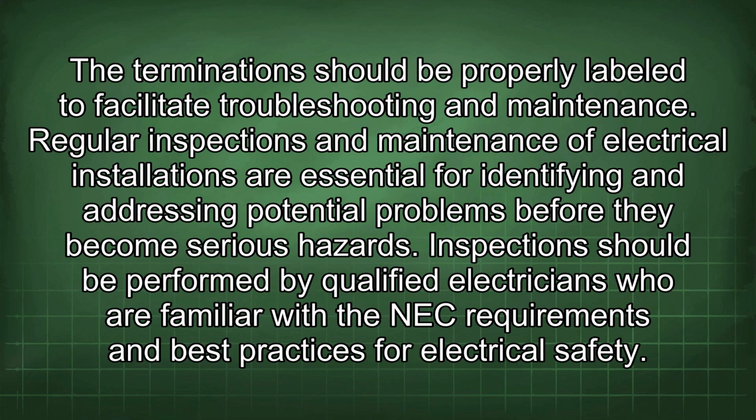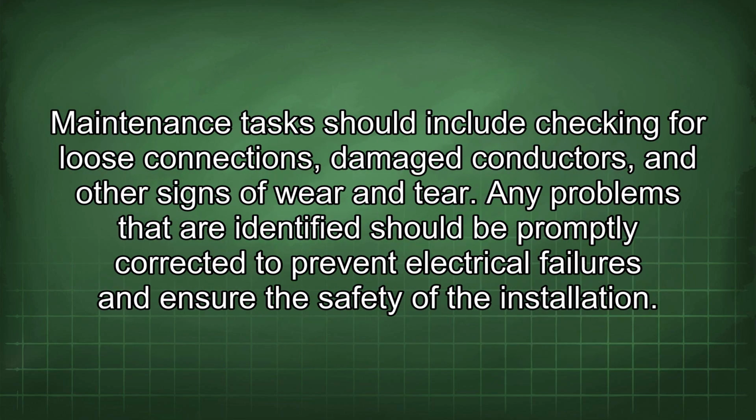Regular inspections and maintenance of electrical installations are essential for identifying and addressing potential problems before they become serious hazards. Inspections should be performed by qualified electricians who are familiar with the NEC requirements and best practices for electrical safety. Maintenance tasks should include checking for loose connections, damaged conductors, and other signs of wear and tear. Any problems that are identified should be promptly corrected to prevent electrical failures and ensure the safety of the installation.